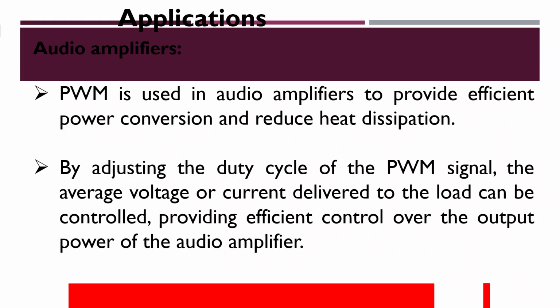To mention it very briefly, PWM, that is pulse width modulation, controls the power by varying the pulse width. It varies only the pulse width, not the voltage. The duty cycle determines the average output voltage. Only by using the duty cycle can the average output voltage be controlled. The frequency usually remains constant, with no change in the frequency, and the average output voltage changes.